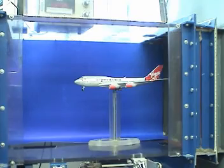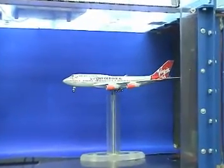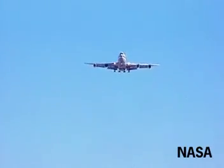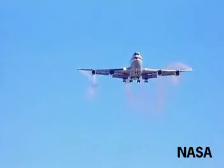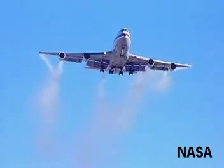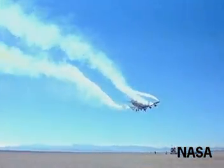We can test a scale model of a commercial jetliner in a wind tunnel, for example, and expect to get results similar to those of the full-scale aircraft, so long as we make sure that the Reynolds and Mach numbers of the model match those of actual flight. A lot of wind tunnel testing, and nowadays CFD as well, go into the design of a commercial jetliner.